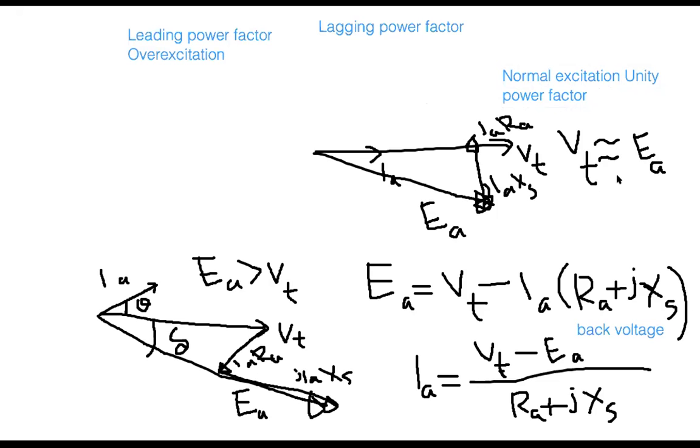So that's why in case of the motor, we got this conclusion. But in case of the synchronous generator, we got the opposite result. The unity power factor case was the same, but this was just the opposite, just the reverse. We got overexcitation during lagging. And in case of leading power factor, we got the underexcitation. But today we got the opposite result. So is everybody fine?